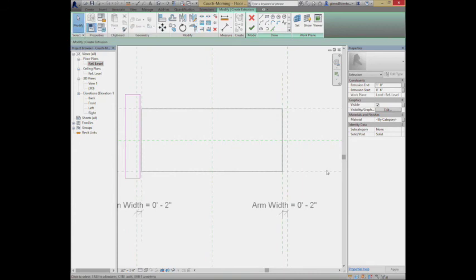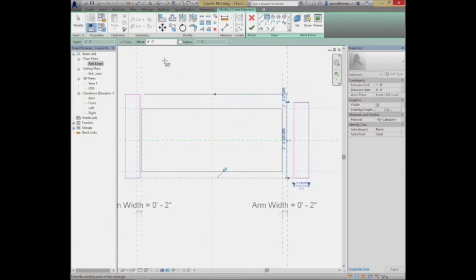As we're doing the arms, if the left arm and the right arm are always going to be the same material and always going to have the same start to the extrusion, you might as well just make them a single extrusion. We can do that just by having 2 loops. 2 loops is okay. They can't overlap, they can't have holes, but they can be 2 loops. That's okay. 2 boundaries.